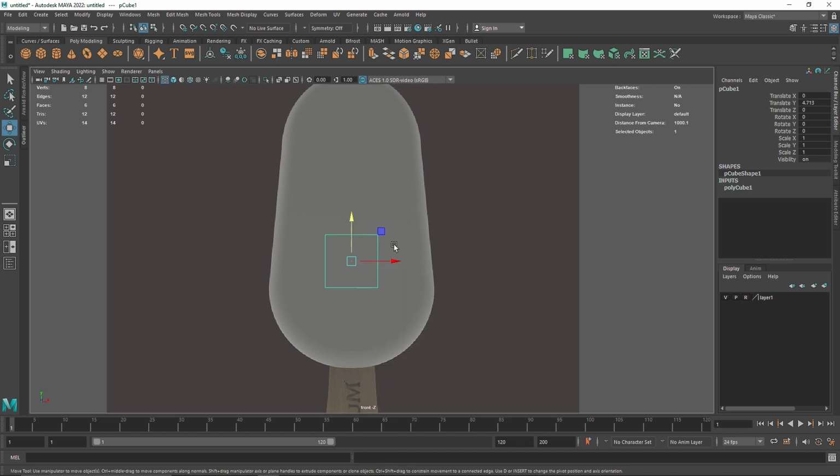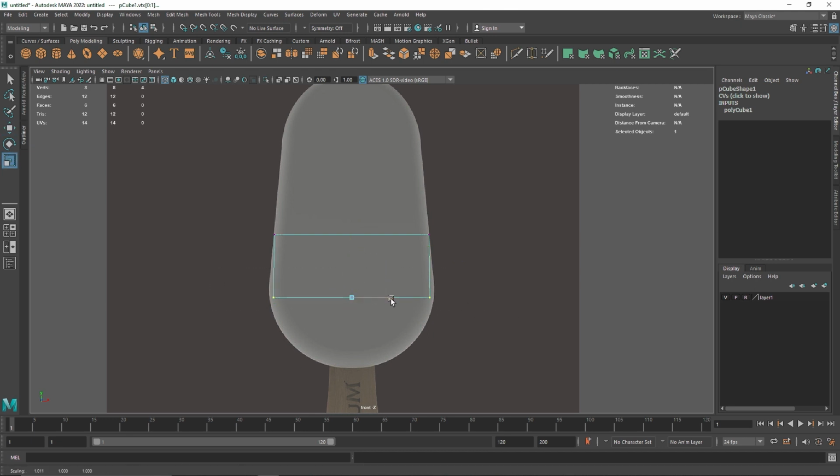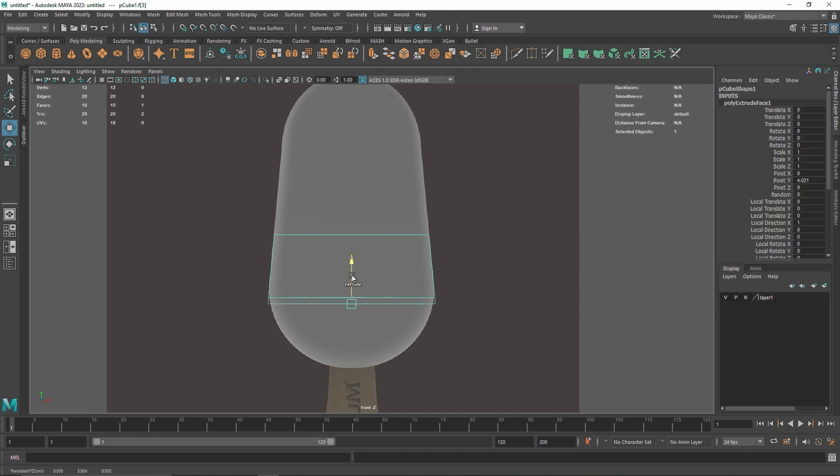Now I'm going to hit R on the keyboard, and let's scale this. All right. Now there's one thing: our image is not perfectly accurate. It's going to be a little bit off here and there. So to make sure your design is perfect, trace only one side, either left or right. For example, I'm going to choose right. I'm going to bring this down, and let's scale this up. Again, I'm going to go to the face mode, select the bottom face, Control-deselect the top face, W, shift and drag. All right, shift and drag, and that's it.